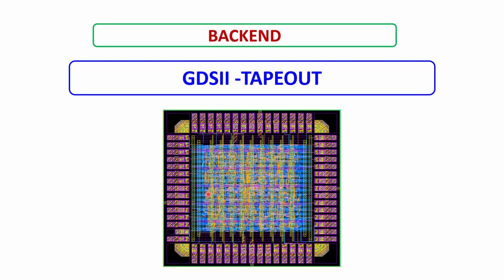Today, we have traveled through the heart of VLSI physical design, from netlist to floor planning, power planning, placement, clock tree synthesis, routing and sign-off. Backend flow is not just connecting wires. It is the transformation of logic into silicon reality. Here, every micron, picosecond and milliwatt matters. Backend design teaches us precision, optimization, and it teaches us responsibility. So remember, front end creates intelligence, backend gives it life.